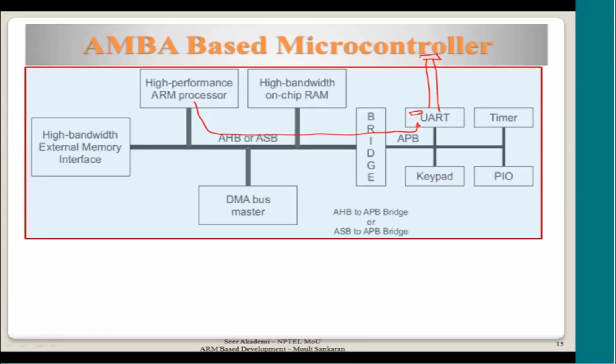The UART will be connected to a PC maybe. Let us assume a PC is there. TXD, RXD, these are the transmit and receive lines. Data flows in this way and data flows here. So characters will be sent over the serial bus at some baud rate, maybe 9600 baud. So 9600 is a standard, and we can say that this is the baud rate.